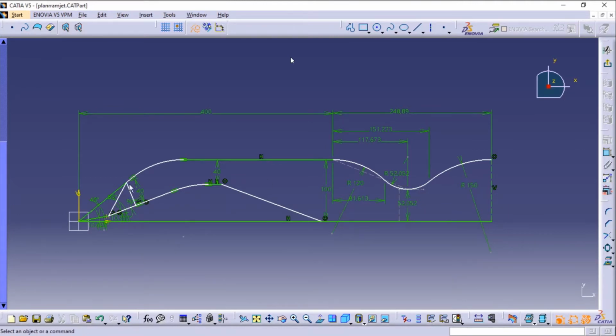So what I was thinking about was calculating the momentum generated, using mass conservation. We could tell how much mass is entering here, since making this area smaller is what increases the Mach number in the outlet, but it decreases the amount of mass flow. I was thinking if I should make a function and optimize it relating the inlet area or the mass flow and the Mach number in the outlet.